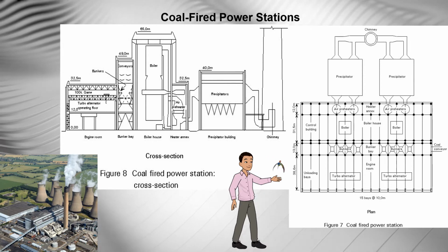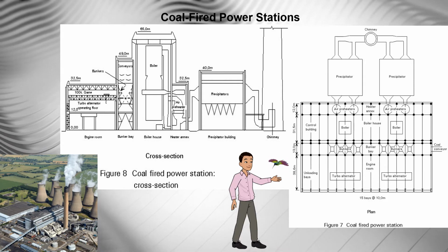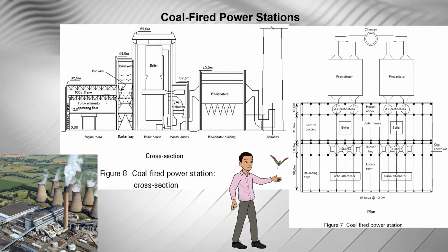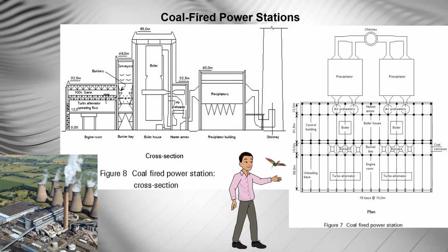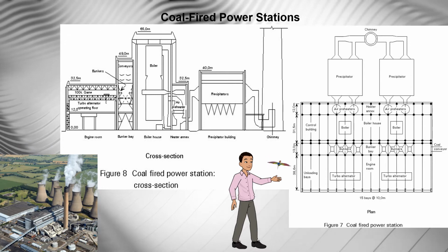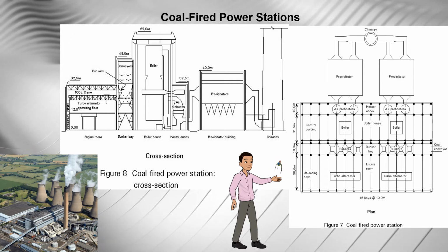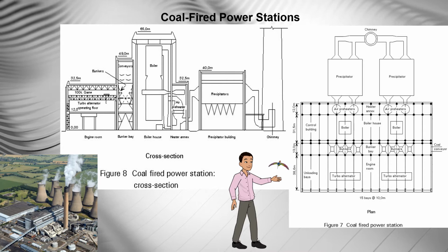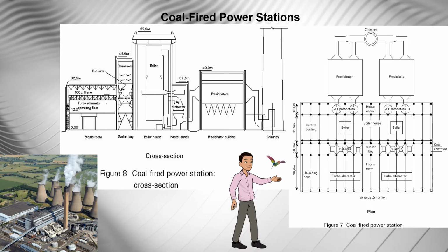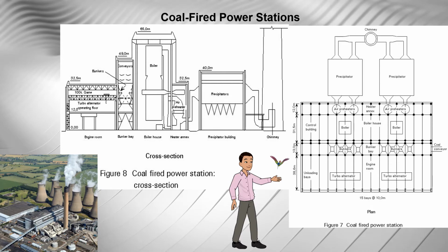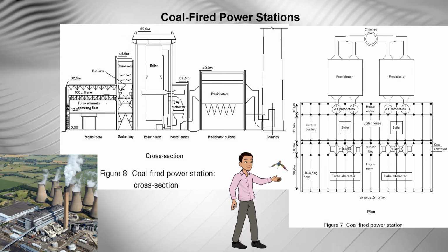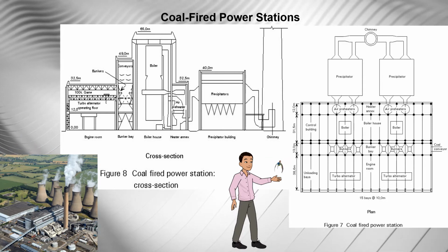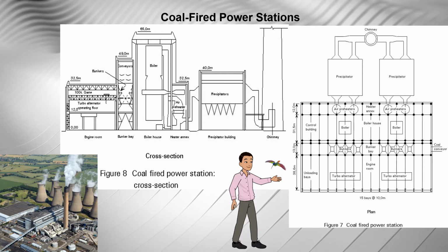The execution of the boiler frame, designed to suit the boiler and from which the boiler is suspended, is central to the schedule. The stanchions of the boiler frame, often 6 in number, are typically compound H section, carrying up to 1,000 tons each, and the boiler is suspended from a heavy plate girder spanning across the stanchions. The external steelwork to the boiler house is relatively light, being mainly supported by the boiler frame, which also braces the building.